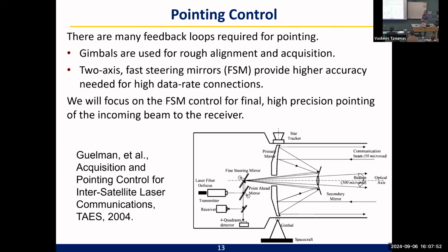So most of the disturbance is coming from onboard systems, is what you're saying? Yeah, a lot of it's coming from this structure, which is not perfectly damped, from the satellite. And so the structural path from the satellite up to the mirrors, that's where a lot of these disturbances are coming from.